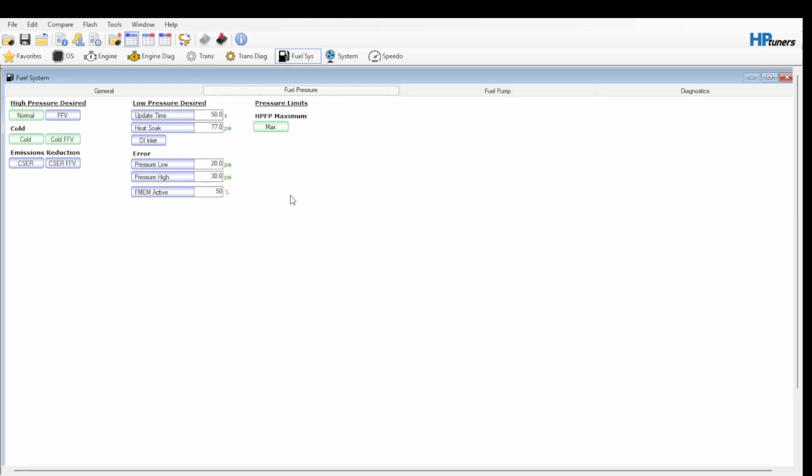But what I'm saying is, get your fuel system in your intake manifold. Don't put it in your cylinders. Your cylinders have enough fuel right where they are. If you can, A, chill the boost down, and B, get more fuel in there, you might need ARP head studs from how much torque you can make.